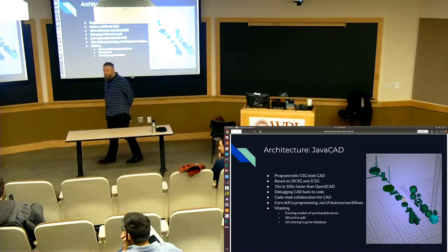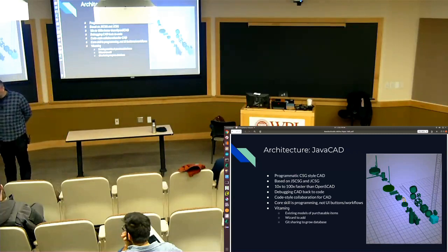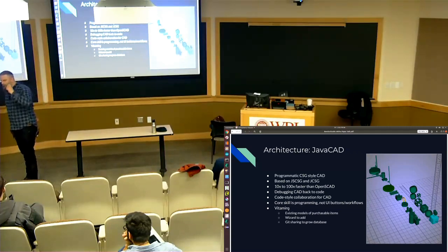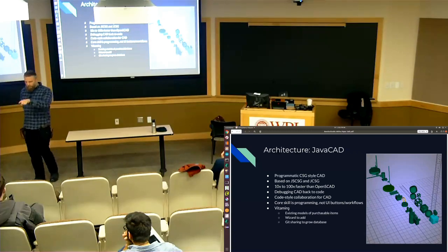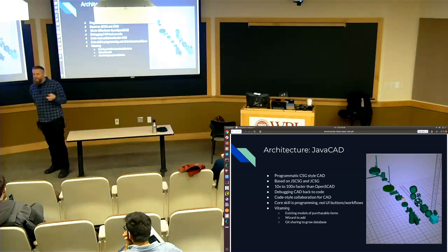You never hit a dead end when doing this kind of designing. You never hit a dead end when you use CSG, as opposed to BREP in SolidWorks. For example, if I need to edit a feature that cascades into other features, I just need to go in and edit a sketch. That's all I need to do. So here's an example of where this problem shows up for that system versus mine. I have a robot cat. The robot cat has captured nuts.